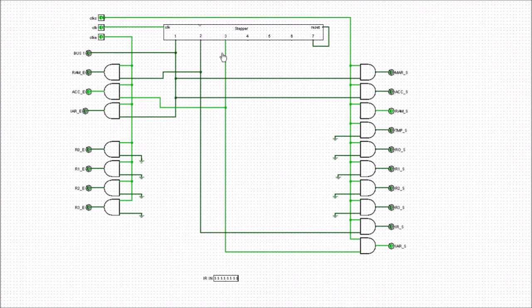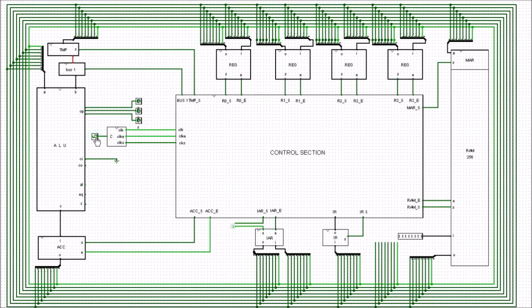So that's us worked through the 3 points here. That's our fetch cycle, and if we were to continue with this, nothing's going to happen for 4, 5 and 6, and then whenever this bus 1 goes high, that's us back to the beginning. The value of 1 would then be incremented because we'd be adding another 1 onto it, and it would have a value of 2, 3, 4, 5, and so on. We'd be beginning and pulling out the information that's in the next memory location. So that is our fetch cycle.